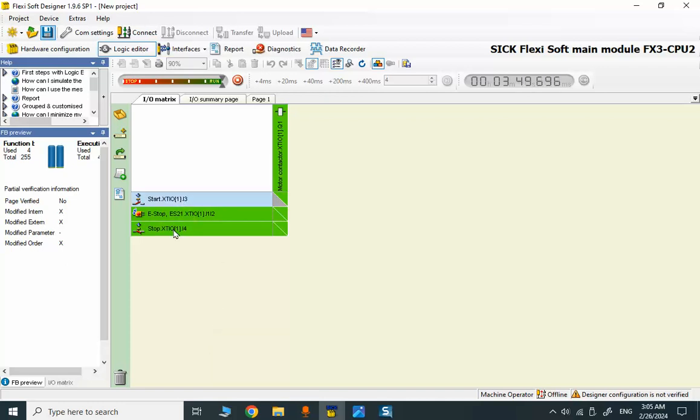All these buttons are inputs from field, and you need to push them from field. So consider we don't have all signals, all emergency signals are false, so it's not possible to run. The first condition should be unlatching the emergency buttons, and just after that pushing the start. It's very easy to do the function test by the IO matrix. It's very helpful for very complex logic possibly.